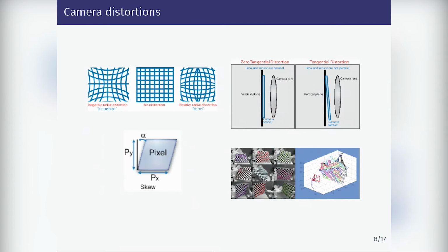When you take a picture with your smartphone, you imagine it as a regular grid of pixels, and everything is fine. But when you want to do anything objective or quantitative with the images, you have to treat all these distortions: pincushion, barrel, because the pixel grid is not going to be regular in reality. Pixels might even be slanted, which is a very weird feature, but it happens. And of course, the lens and the image sensor might be misaligned in very weird ways.